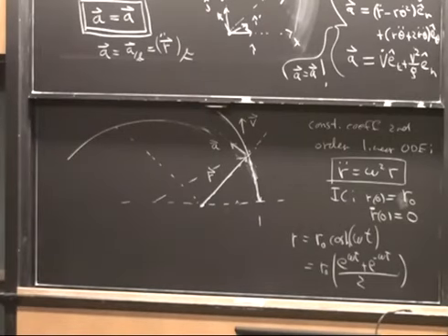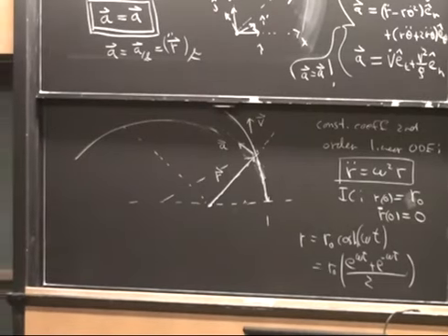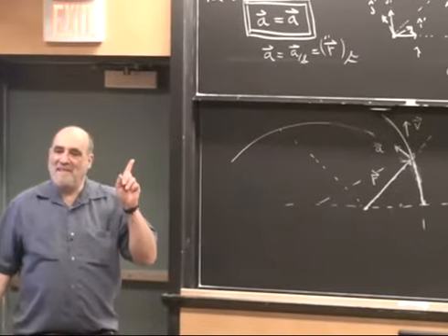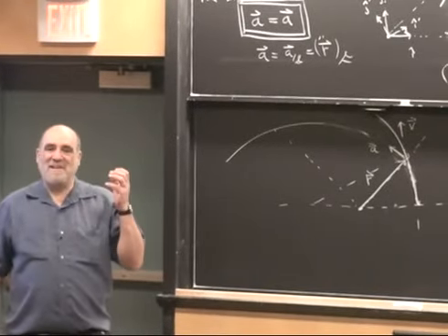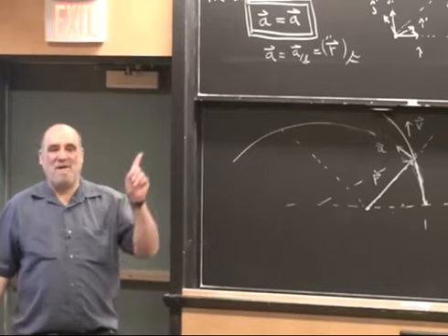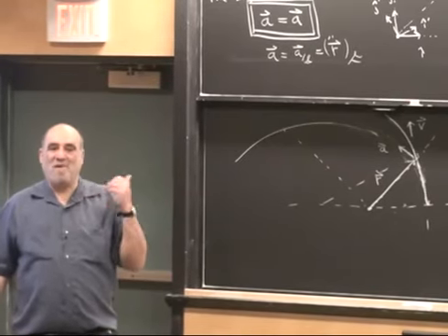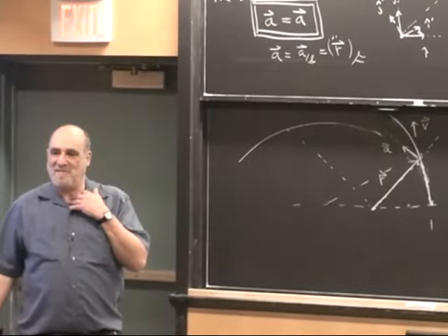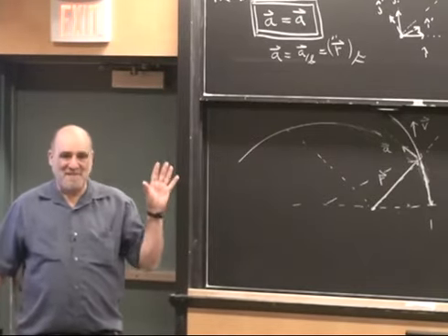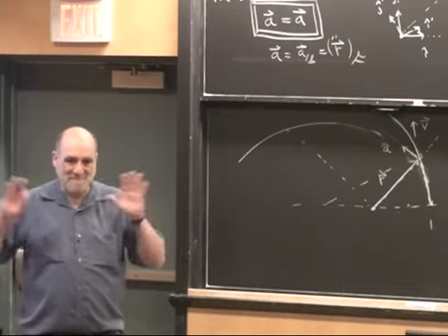So at every instant in time, any particle, no matter how it's moving, you can look at its path, find the circle which is intimate with it, and its acceleration has two parts. One part along the tangent to the circle, and one part normal to the circle. And the part normal is v squared divided by the radius of the circle. Okay, any questions? Everybody happy? Goodbye.